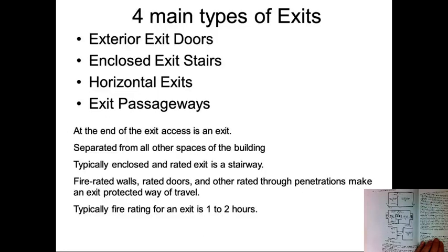There are 4 main types of exits. You have exterior exit doors, enclosed exit stairs, horizontal exits, and exit passageways. Remember, at the end of the exit access is an exit. It is separated from all spaces of the building, typically an enclosed and rated exit stairway.